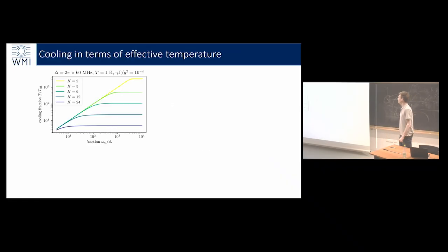So we fixed here parameters to something which we think is realistically available on the platform. So dissipation of 10 to the minus 4. We go to 1 Kelvin, which is roughly the highest temperature we think we can use, because afterwards the superconductivity will break down. And we use the longest waveguide we can have just to increase the cooling effect, so to say. And then what we tune is this fraction of the lower temperature, and a plot by which fraction we can decrease with respect to the physical temperature.